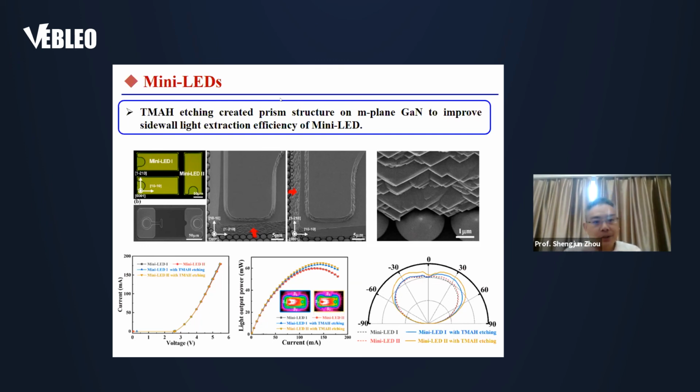Compared to square indium gallium nitride quantum well, electron hole wavefunction overlap of staggered indium gallium nitride quantum well exhibits a 1.7-fold improvement. Staggered indium gallium nitride quantum well shows uniform elemental distribution and better crystal quality, thus leading to a higher light output power in yellow LED.